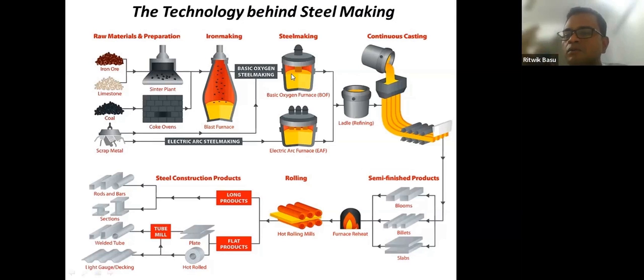So steels, as you know, are classified into plain carbon steels and their alloyed counterparts, and also stainless steels. Typically or traditionally, this process starts in a blast furnace where raw materials like iron ore, coke, pellets, etc., are added from the top. And at the bottom, you have this hot molten material containing around 4% carbon. So this process is usually assisted through a series of reduction and carburizing steps.